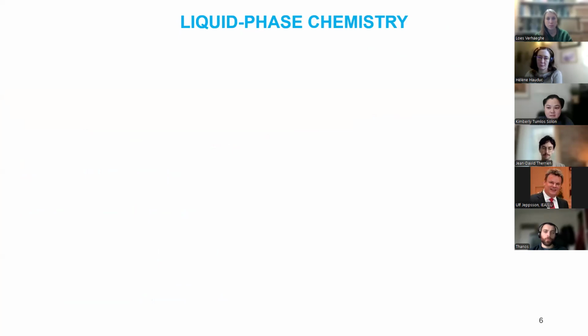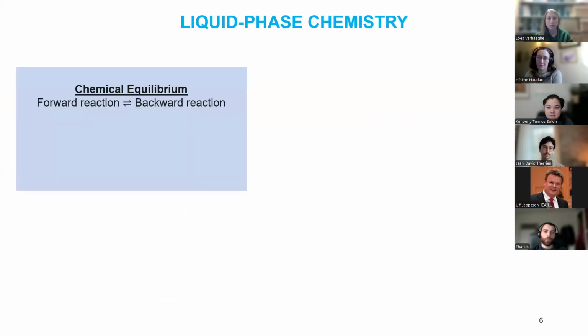Now, one crucial principle in aqueous phase chemistry is chemical equilibrium. This is quite basic, but I want to go back to this as well. So liquid phase chemistry modeling depends heavily on the chemical equilibrium theory. Why? Because liquid phase reactions in wastewater are very, very fast. So as I said, milliseconds. So that within any practical wastewater time frame, these reactions are always at equilibrium.